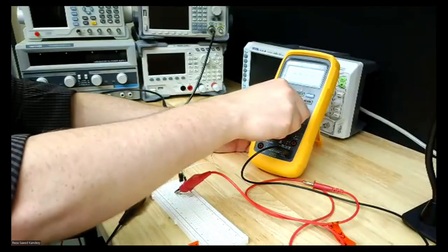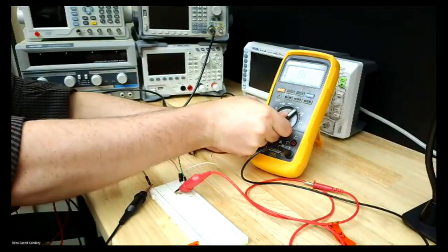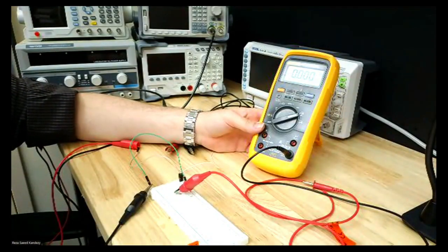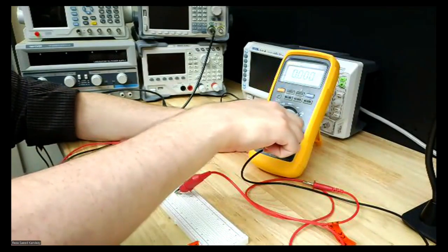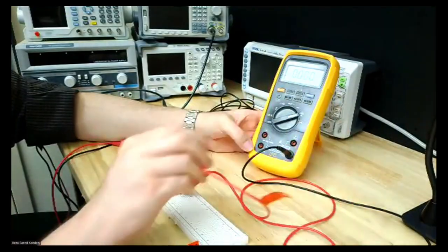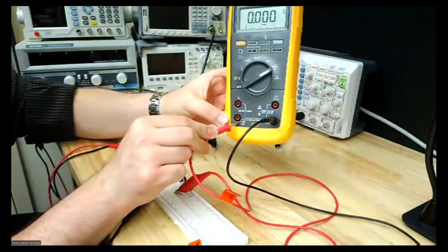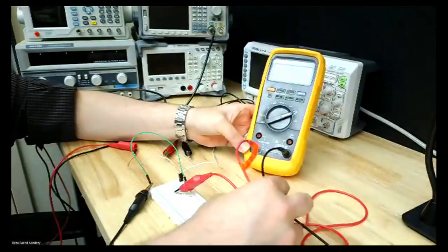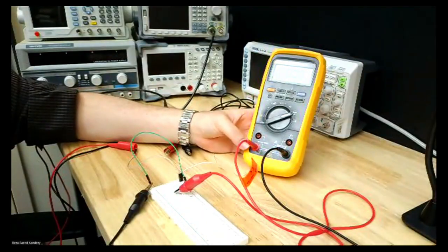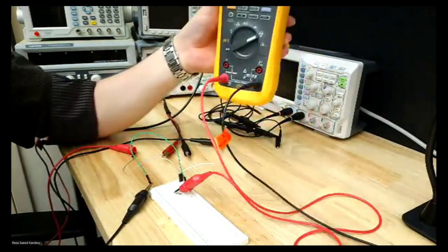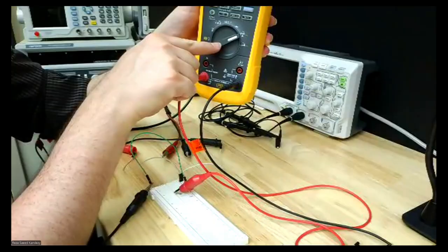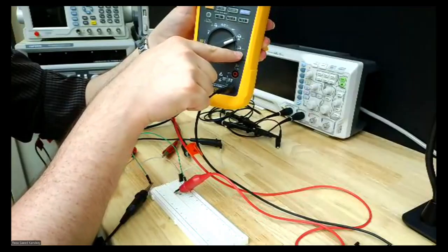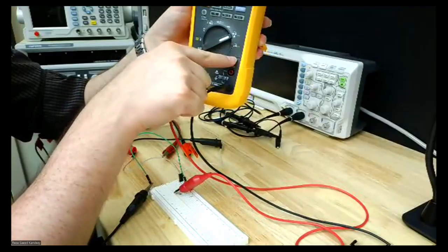We are going to put our setting to the DC amp, and we have two types of range. We expect a milliamp, so I'm going to set that to the milliamp. And the milliamp port is the bottom one here. Okay, so I'm going to put my probe connected to that port. Now, one thing to pay attention to is that, different from the volt, the amp and milliamp for DC and AC have the same probe.